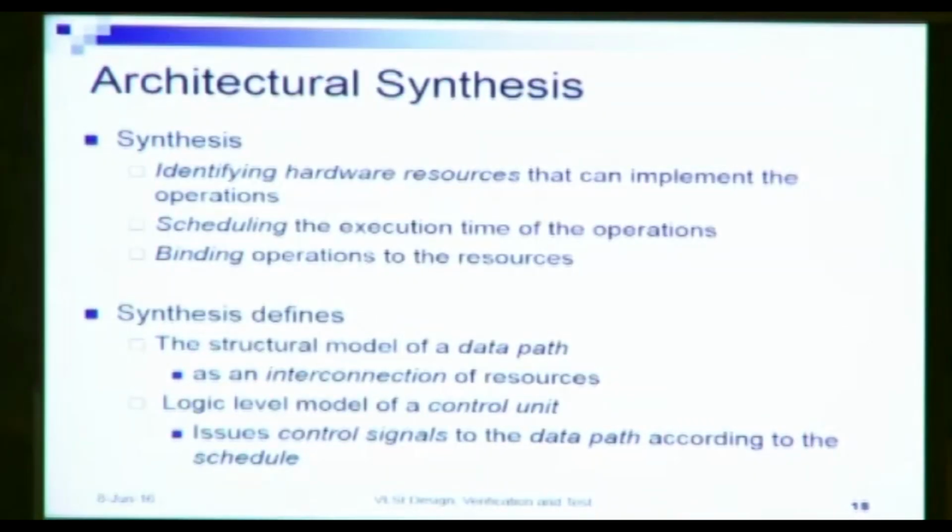Then we have to schedule the operations in different time steps. So scheduling the execution time of the operations. We have to schedule the operations at distinct time steps. And then we have to bind these operations to the hardware resources that we have identified. So the synthesis goes through these three major steps: identifying the hardware resources, scheduling the operations into time steps, and then binding the operations to the hardware resources.